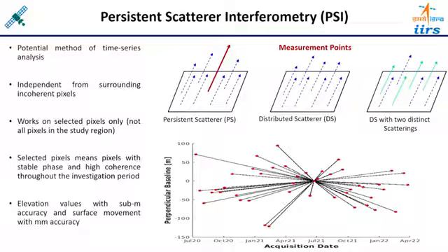Okay. And the drawback of this technique is, suppose you have taken a large baseline, 10 years of data, so a 5 years gap is there on either side. Suppose some region is so dynamic that the features are changing very rapidly, and hence the signals become completely decorrelated, because 5 years is not a short time. If you are working in a forest region, in 5 years the canopy structures of the entire forest will be different.